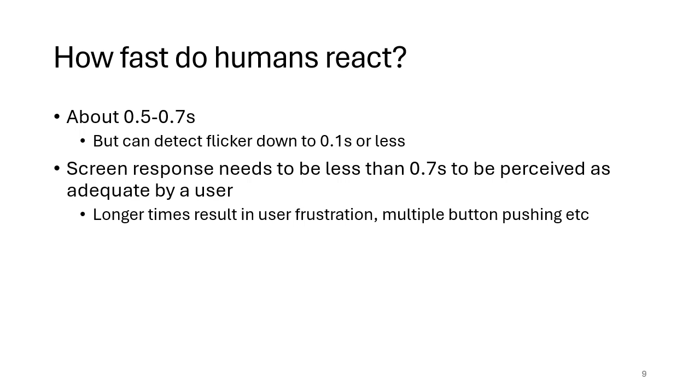Something that I think is of less importance but often comes up in conversations is about screen response time. But this is important because again, this can result in operators who aren't happy with the solution, particularly if things take too long to happen. I think we're used now with websites where you click on a button and it can take a few seconds to load a new screen. We often see specifications where they ask for 2 seconds or less to change screens and 1 second or less for response time on the screen.